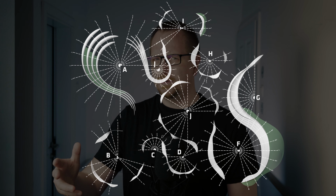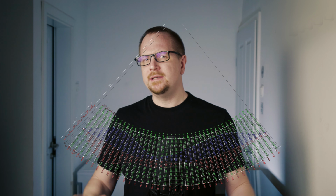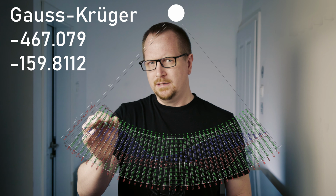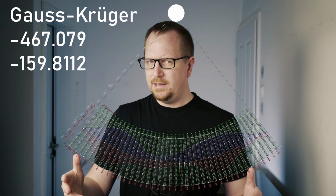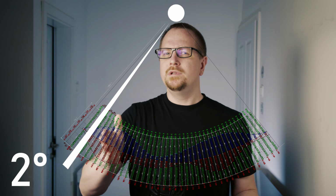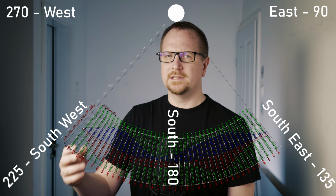Let me explain the process of describing the shapes for the construction drawings. We divided the project into semicircular parts. Each part has a central point, which is exactly positioned in space. From that point, everything is measured. We cut our shape every 2 degrees. The name of the section is also the direction of the sky. This is to have redundancy of information and to help prevent confusion on the building site.